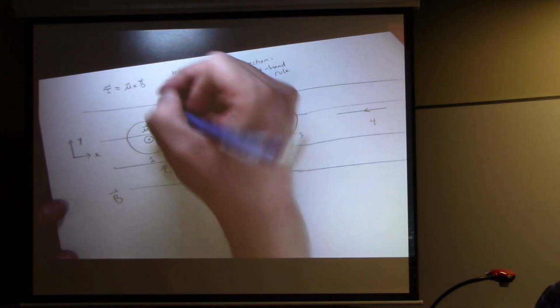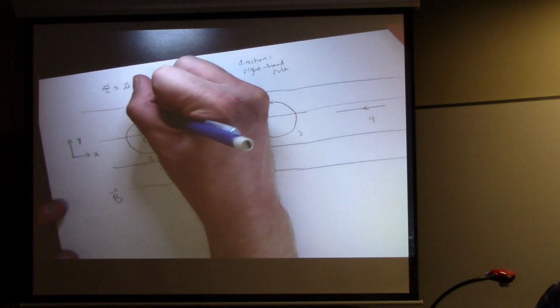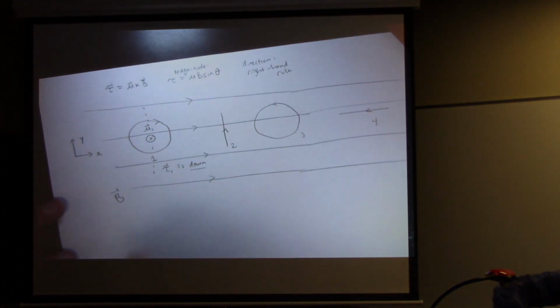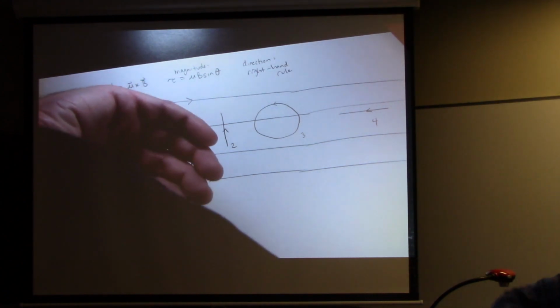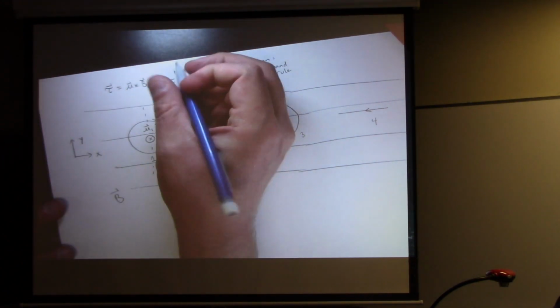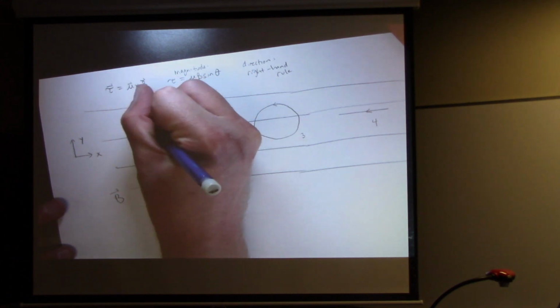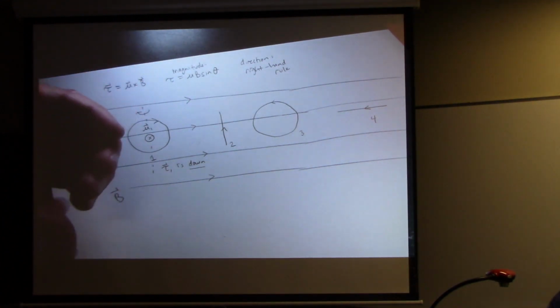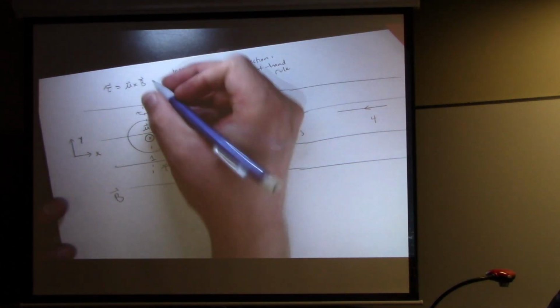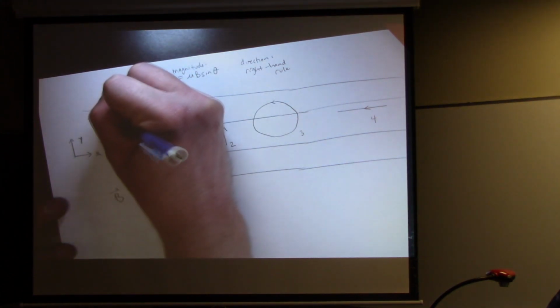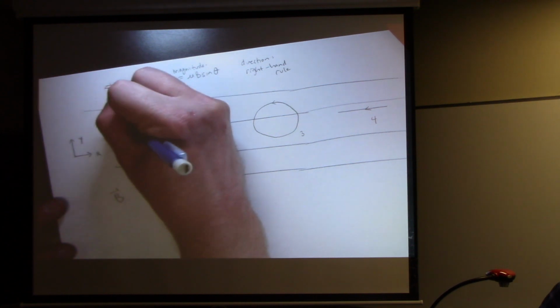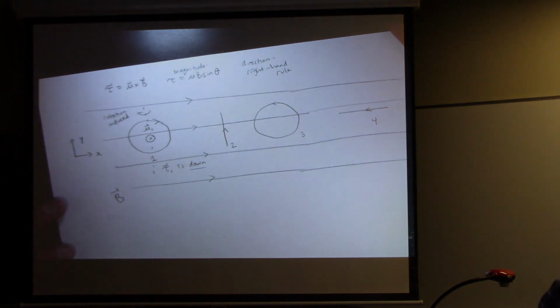And here, let's think about what that means. So if I have a torque that's going down, that's showing me that this is inducing a rotation like this. Okay, so if you point your thumb down and you curl your fingers of your right hand, you'll see that it's inducing a rotation basically around the y-axis. So that's my rotation induced.